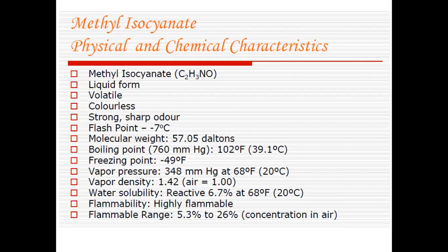Liquid form, volatile, colorless, strong sharp odor, flash point -7 degrees centigrade, molecular weight 57.05 daltons, boiling point 102 degrees Fahrenheit, freezing point -49 degrees Fahrenheit, vapor pressure 348 mmHg at 68 degrees Fahrenheit, vapor density 1.42, water solubility reactive 6.7% at 68 degrees Fahrenheit, flammability highly flammable, range 5.3% to 26% concentration in air. These are the physical and chemical characteristics of MIC. At least you know some points, some characteristics of the MIC. Okay.